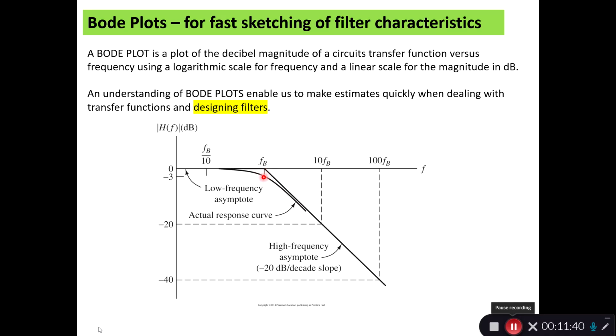So in a normal setting, when we have to design for a low pass filter, the Bode plot starts at the break frequency divided by 10. Then we have the break. So up to this point we draw with a ruler as a straight line. At the break frequency we have a direct slope of minus 20 dB per decade. So this is the magnitude sketch in dB.